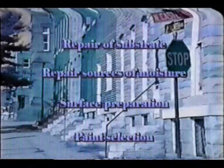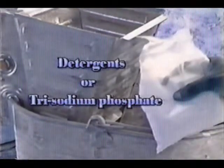Paint film stabilization involves the essential elements of residential painting. These elements include the repair of substrates and any sources of moisture, followed by proper surface preparation and paint selection. The keys to proper surface preparation include removal of all loose paint by hand scraping or sanding the surface after it has been misted with water, reduction of any surface gloss by wet sanding or chemical etching, removal of all surface contaminants by cleaning with detergents or trisodium phosphate and then water.